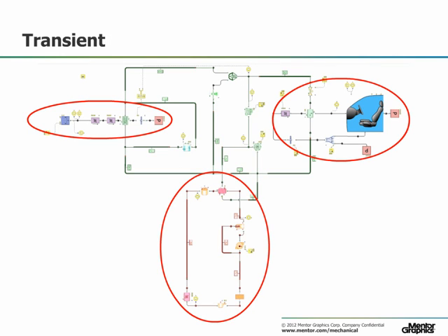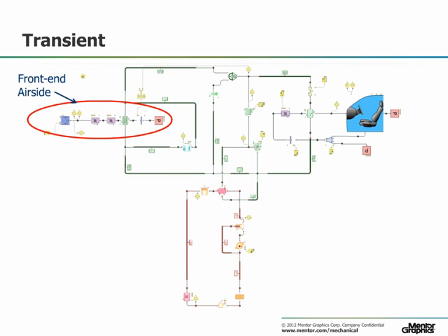For a better picture of the various transient thermal interactions, the model has been expanded to include cross-flow paths for the heat exchangers. On the air side, a stagnation pressure source has been used to account for vehicle velocity when calculating the boundary pressure. A couple heater-cooler components are also in the airside circuit to model additional heat gains from sources such as the charge air cooler and condenser. A fan is also included to move air across the radiator.